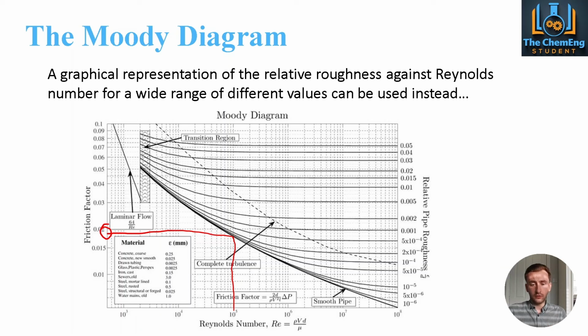There is, of course, you could substitute in the values to the Colebrook equation, and you should end up with a similar value. Again, the equation will give you a more accurate value, but in ease of simplicity, the Moody diagram, you will get a rough estimate much quicker without the need of an iterative calculation.